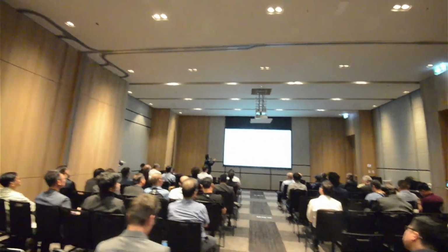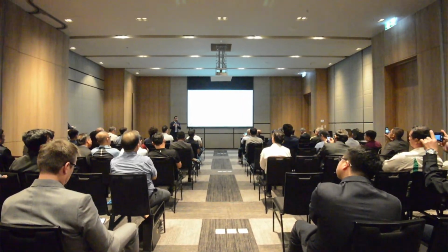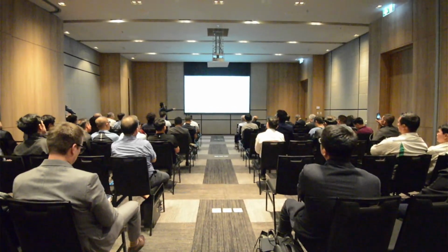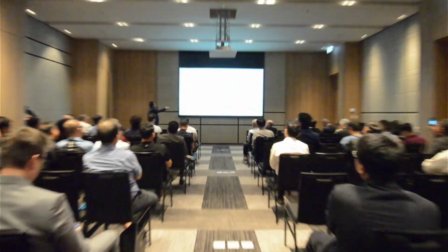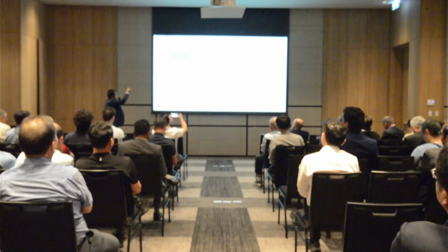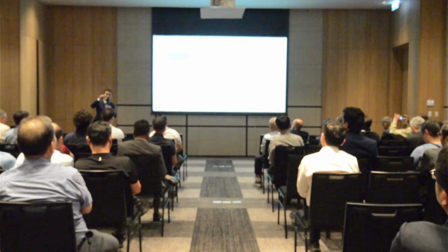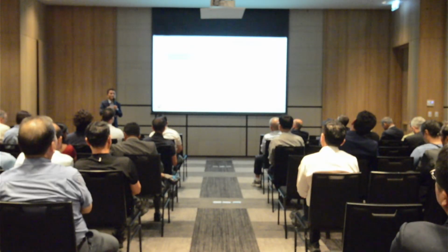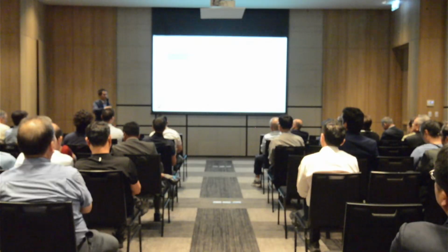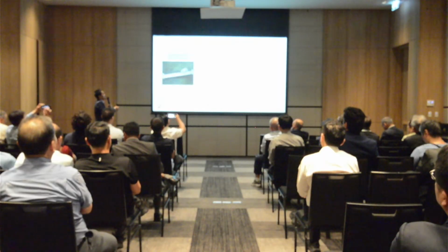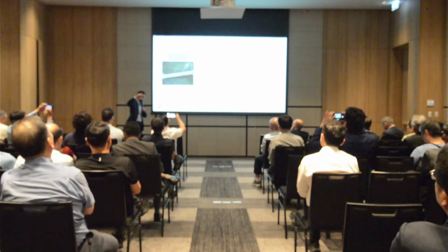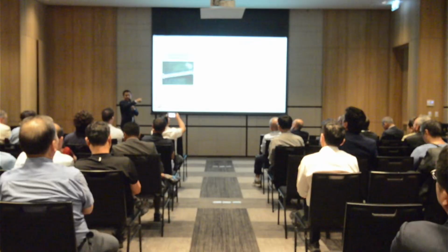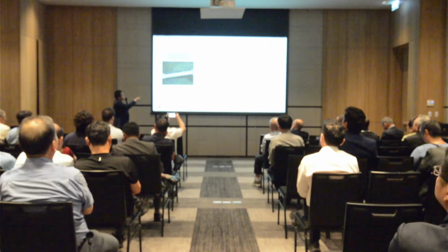First, normally for liquid castings, we have some superheat. It's fully liquid, and we start here, and go to lower solid fraction. When we go below the liquidus, we get into the liquid-solid range. It's like semi-solid. In semi-solid, if the solid fraction is 5%, 10%, 20%, it still can flow like a liquid. We call it a low solid fraction. And once it continues cooling down to lower temperature, near the eutectic temperature of 575, you will get a high solid fraction like a slug.